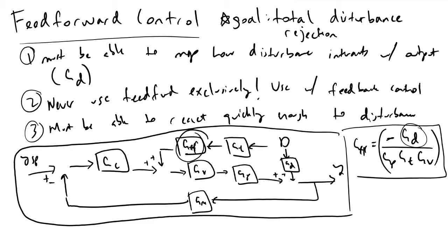And so to test if your feed-forward controller is working, you analyze the time response of your system, and we'll have some kind of step time. So if we went into Simulink and we had our disturbance variable D here suddenly go up to a certain value, like if we had our wind speed suddenly increase to 10 miles per hour in the southwest direction, it would occur at 1 second in our model. That would be our step time TS.